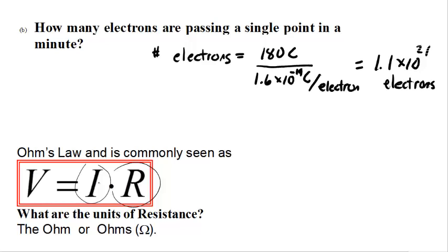Sometimes it's done intentionally, where people will put resistors in the circuit because the current is too high and will blow up your light bulb or something. Other times it just comes with your circuit, and almost everything you add to a circuit will have resistance. Resistors, of course, will have resistance. Different components of your circuit, even the wires itself will have resistance, and the longer wire you use, the more resistance you'll have. Even the battery has something called internal resistance.